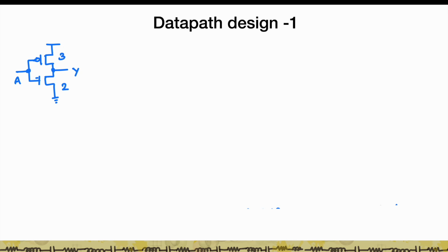So let's first start. Typically in problems like this, it's a good idea to first figure out the critical path and then figure out all the logical efforts, parasitic delays, branching efforts, etc. The smallest inverter in this technology is a 3.2 inverter, that's PMOS size 3 and NMOS size 2, with an input capacitance of 5.